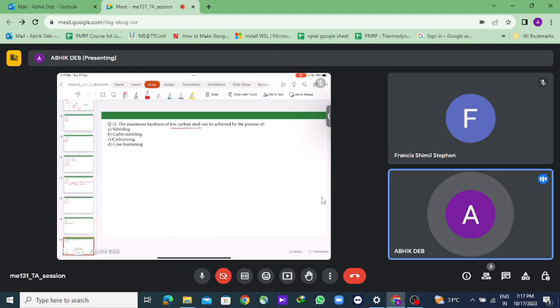So actually, they are talking about nitriding, but they have specified it for alloy steel. For alloy steels, the surface nitriding is a treatment in which nitrogen is diffused into surface of special alloy steel to produce thin hard casing. So in that they have mentioned that it should contain chromium and aluminium for better effectiveness.